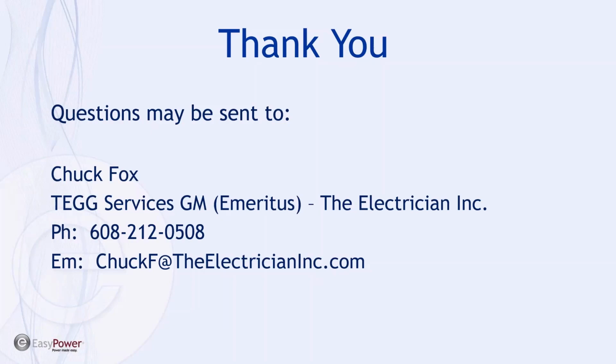Is it mandatory? Under chapter 7 of the 70B standard, the title of that chapter is now referred to as fundamental tests. So within that specific section, infrared is considered a required fundamental test. And there's additional ones of insulation resistance testing, torque verification, and contact resistance as well, being elements of test protocols that ultimately can be part of your test and inspection programs. So when you look at that scheme of, we're going to look at our inventory, we should be doing this test and inspections, what ultimately should be in there.